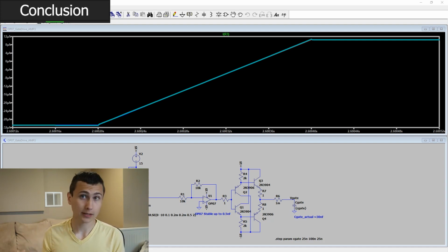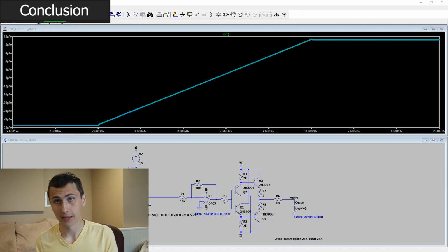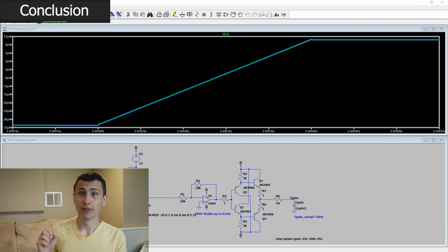These are not built on the same wafer. These are not complementary pairs. And what that means functionally is that their gains, their forward voltages, their temperature effects, those types of parasitic effects aren't going to be perfectly matched.